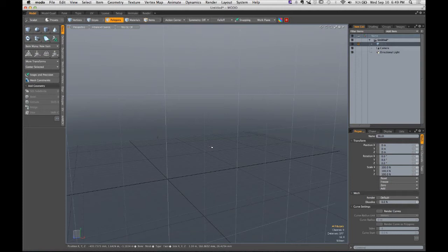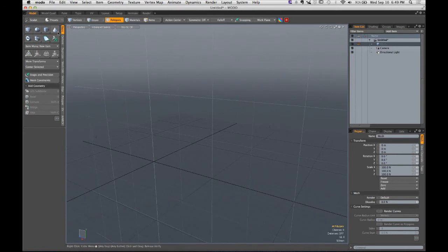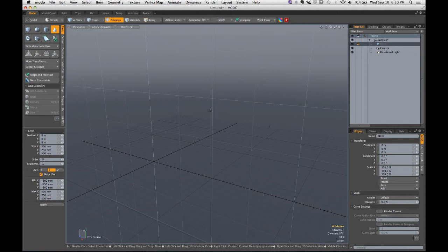So now that we have a little bit of mastery with the square tool and the cube tool, let's advance on just for one second and explore the cone tool. The cone tool is kind of fun. It behaves almost identically to the cylinder tool initially. So if I wanted to create a perfect cone, single left click, move my cursor away from the tool handles, hold the control key, and then left click and drag.